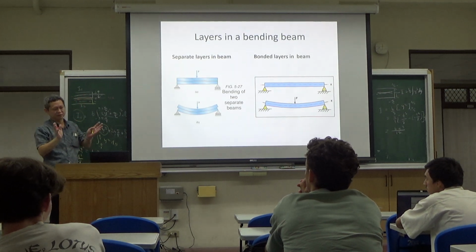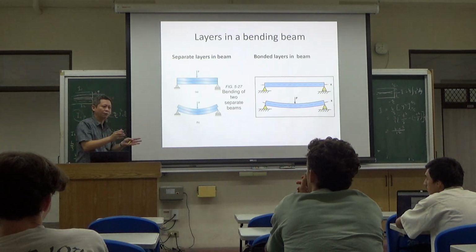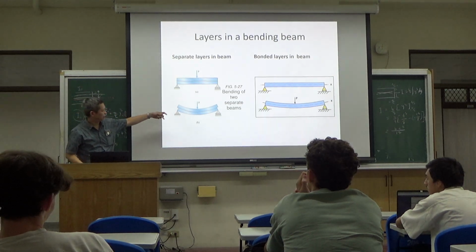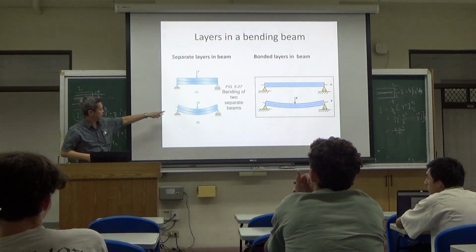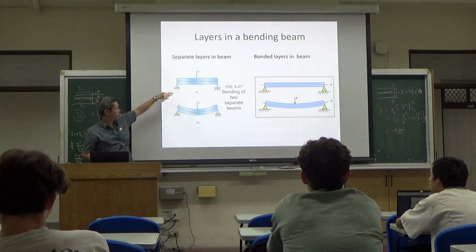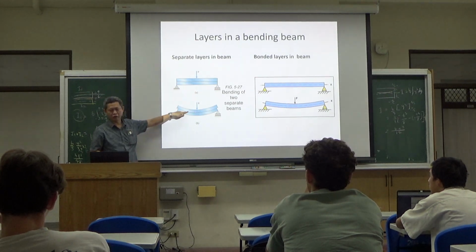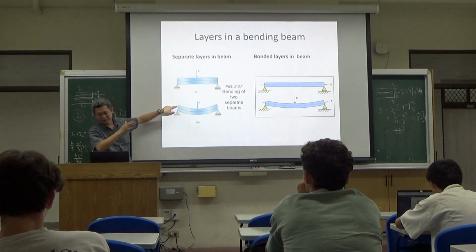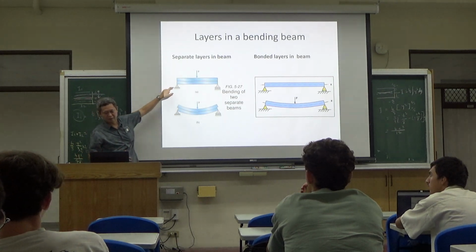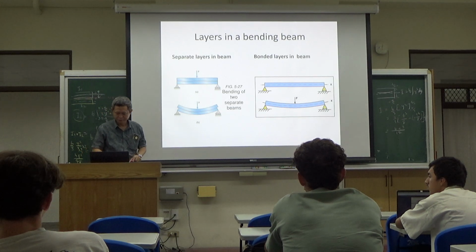They have the skin inside, outside, and the middle is honeycomb, and then the layers are riveted together. Once riveted, it is joined together. Even though there may not be a common structure bonded throughout, because of the very short distance riveting, you can make them a more integrated multiple layer.